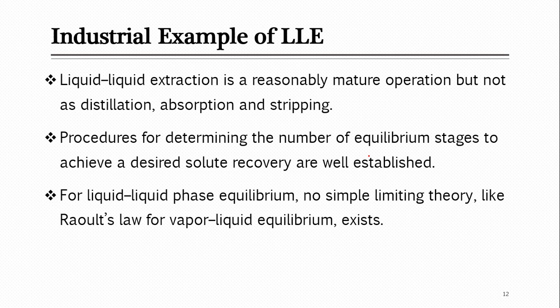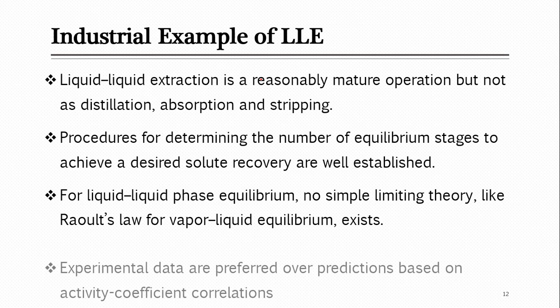But for calculating liquid phase equilibrium, there are simple limiting theories, like Raoult's law which we discussed for absorption as well as distillation. Those are well established theories, but here in liquid extraction, for equilibrium calculation, we don't have such a well established theory.